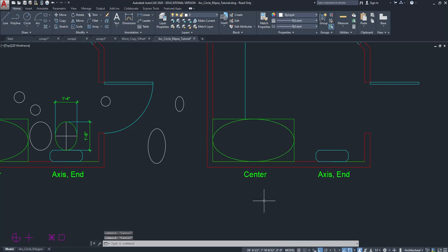Okay. So the rectangle command, it's a polygon and it's on the draw tool palette up here on the home tab. We have rectangle here. I'm not gonna worry about polygon just yet. But rectangle, I click on it and I can initiate a rectangle, okay? So I can create a rectangle by eye if I wanted to. I can just sketch something. Click, move in the direction I want to go, click again, there's my rectangle, okay?